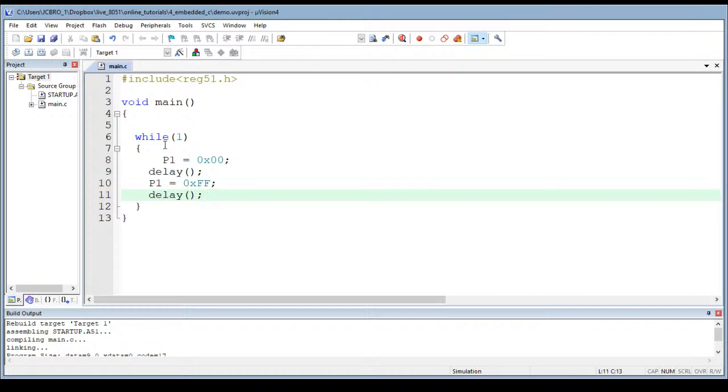We have learned in our earlier video how to compute the delay of 1 second if we are writing in assembly language programming. But in the case of C language, we don't have that liberty, because we can't exactly know how that particular code is being transferred into the assembly language program, so we cannot compute the delay like we did in assembly language. So in this case, we will apply a different trick. We will compute a delay, and then we will see that amount of delay on a CRO, or you can say on some function generator.